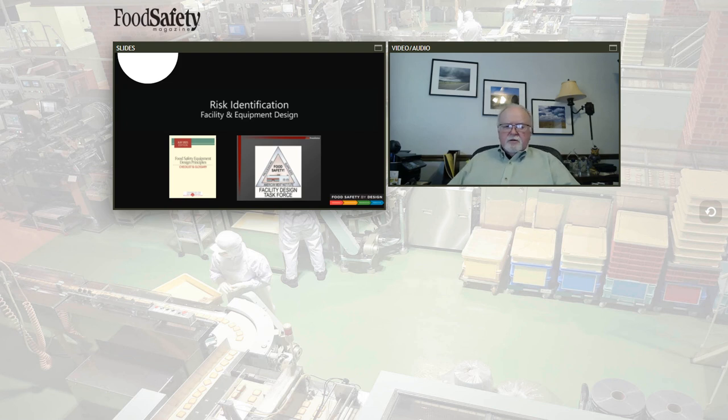The plant team must be skilled in risk identification. I think Bob did a good job of identifying that plant team. They use the principles of sanitary design as the basis for risk identification. These include wet floors and failure to effectively separate hygienic zones, raw to cook, for instance. Now, these two documents represent a total of 121 principles and 229 individual criteria elements of sanitary design. We must view sanitary design violations and deviations much the same as we view potential hazards in our HACCP plan.